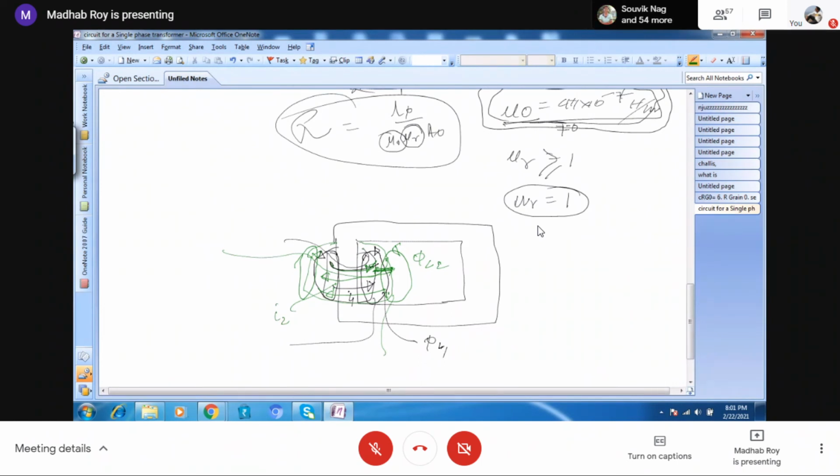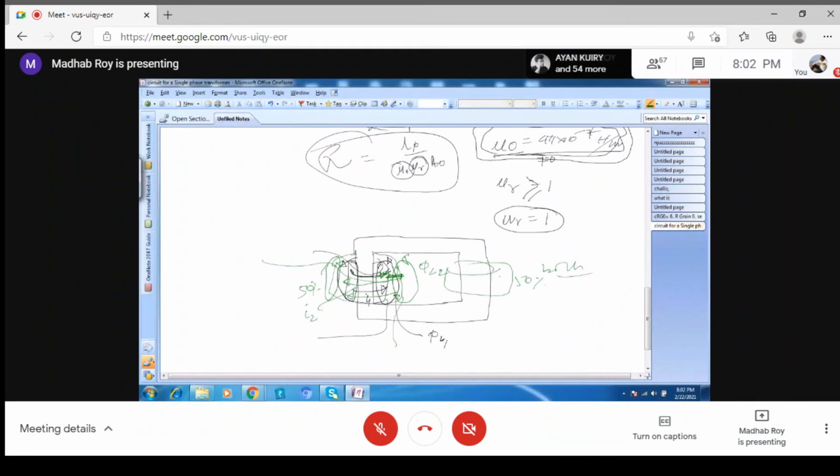Okay, so that's why transformers always prefer any winding 50% on one leg. Both the primary and secondary must be on 50% of the one leg. Another 50% will be here also. This will be a further 50% of both. So thus the transformer is designed and manufactured so that the leakage flux is tackled. That is the main design aspect, the minimization process of the leakage flux and the leakage reactance.